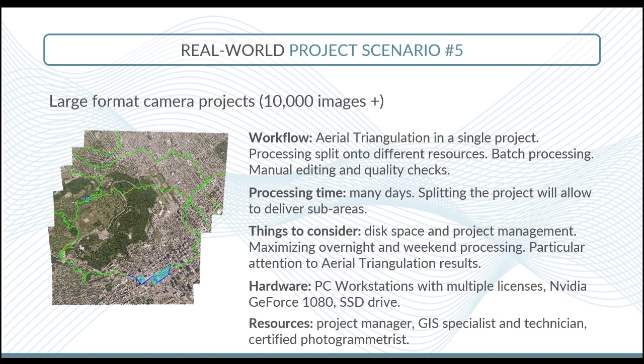In terms of workflow, if possible, I would say try to do the aerial triangulation in one single Correlator3D project. Especially if your block is very continuous, like a big block like this, even if you have 15, 20,000 images, you can run the aerial triangulation in one single block.